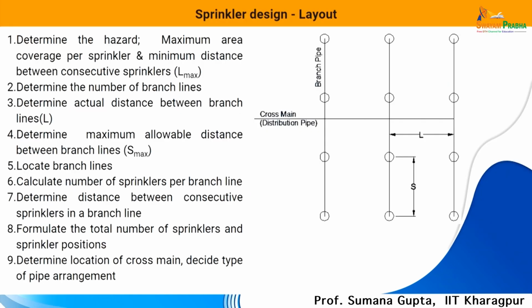However, we move to the simpler part, which as architects we need to know, which is the sprinkler design or its layout. So, what you see here, a schematic has been given. As you see, L is the distance between the pipes and S is the distance between the sprinklers. S gives sprinkler and distance between the pipe is given by L, and there are again standards given for normal or ordinary conditions, what should be the maximum L and what should be the maximum distance between the two sprinklers.